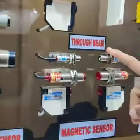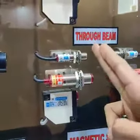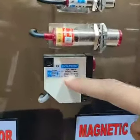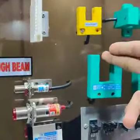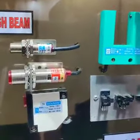We have the through beam type sensor, in which we have one transmitter and one receiver. Any object that obstructs it, the sensor would give an output. The operating voltage is about 10 to 35 volt DC. Now we have the slot shape sensor. Slot shape sensors are U-shaped body type, and when the target will obstruct, the sensor would give the output. It has both transmitter and receiver.